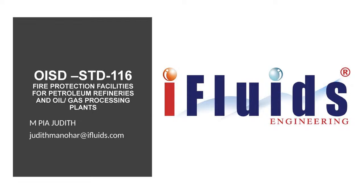With respect to the fire alarm, your response action will be defined in the emergency procedures. So what are the precautionary actions taken with this fire alarm? For example, any operator can go and inspect which valve or flange is leaking, or if you have two out of two, or two out of n detector alarms, confirming the gas alarms, there may be a possibility of configuring a shutdown valve, or activating a major fire protection system. All these executive actions will be configured in the control group of this fire and gas detection system. So that's how the entire system works.